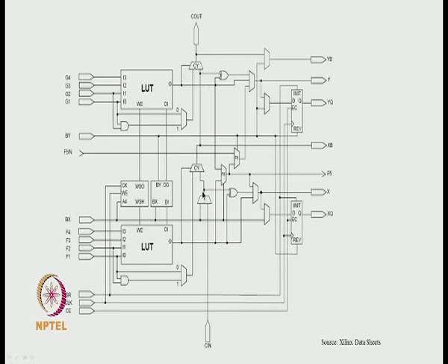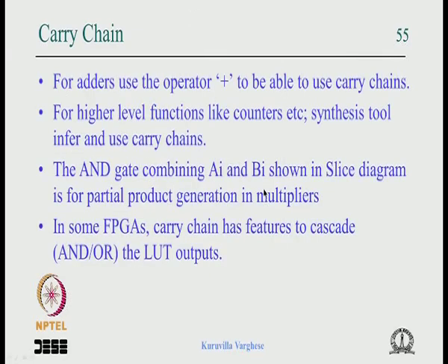It goes like that, and you can see there is an input mux in this stage. This allows, if you are starting, the 0th stage of the adder is this stage, then you can have a carry input to the stage. Like the first stage can have a C0 or C in 0. So that is what this is for, which is not available here. It will be available only in the next slice. So that is how it goes. I hope that is clear to you.